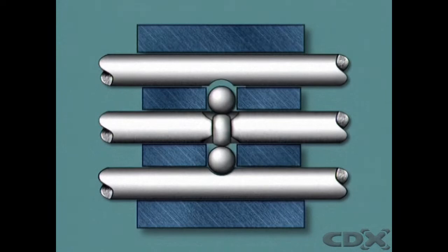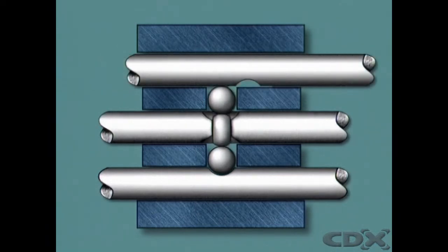In the neutral position, the balls and plunger can move laterally. But when an outside rail is moved, the ball is pushed sideways to contact the plunger and move the opposite ball into the groove of the other outside rail. The 2 balls held in the casing prevent movement of the interlocked rails and hold them in the neutral position.